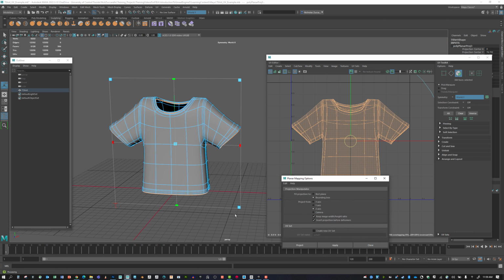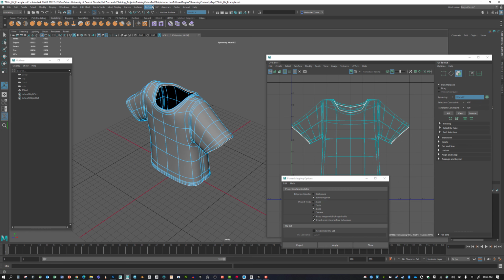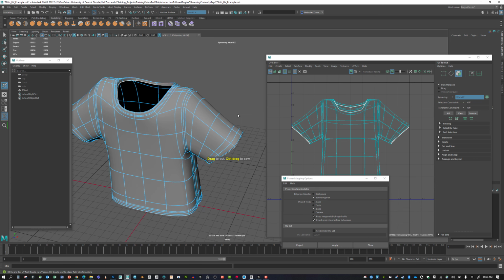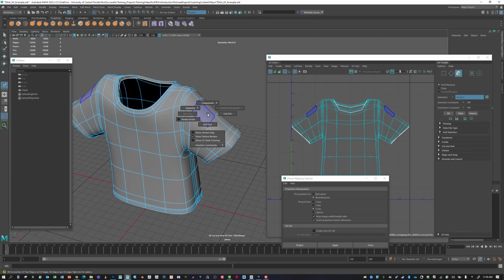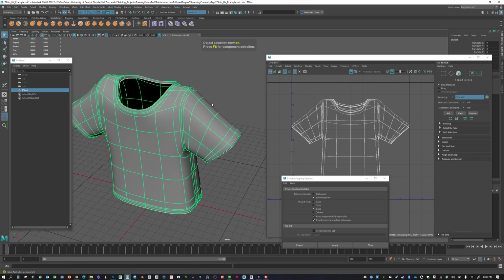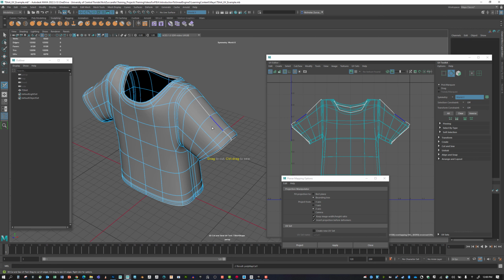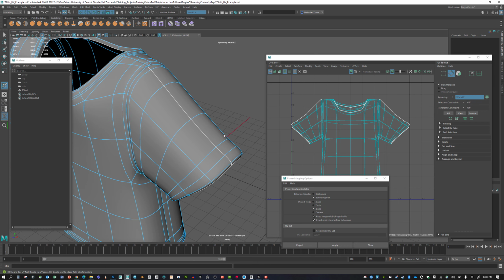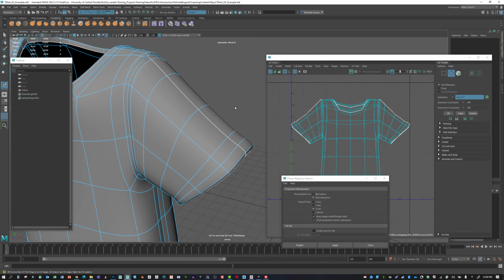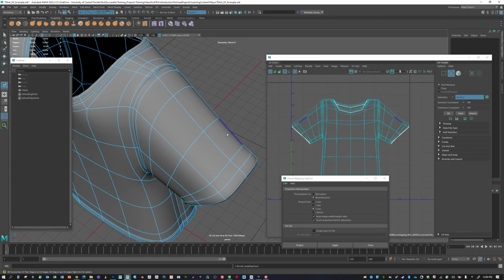And the next thing I'm going to do is use what they've got called a UV 3D cut and sew UV tool. Okay, and so I'm going to right click on here and go to cut UVs. I am on edges for this thing, so if I hit F8 and got out of the tool, and I just click this and right click, say edge, and then go back into that tool, you want to make sure you're in the edge mode for this. So if I just double click on that, that's going to split these things apart, and you can see it's a thicker line like this, and if I hold down control and double click, it'll sew it back up.